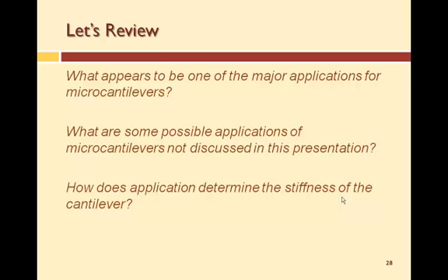Deformable mirror? Yeah, it does. You pull down the cantilever switch with an electrostatic force or a voltage. You pull down the deformable mirror with an electrostatic voltage as well. It's the same principle. Except in the case of the deformable mirror, you usually have an array of voltages, and they're each accessed separately.